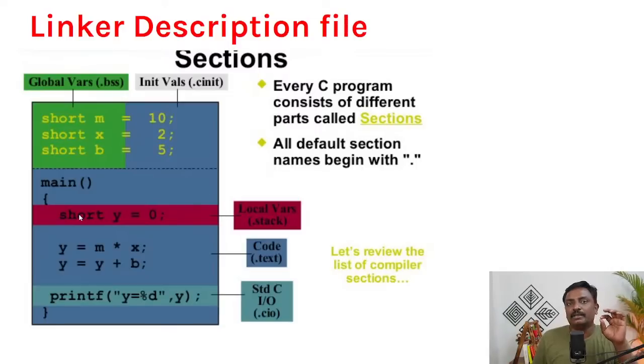Whenever you go for a microcontroller, there are two types of memory available. One is the flash memory, which is non-volatile. The other is the volatile memory, which is the RAM. When you do arithmetic operations, the variable value will be changed, so you cannot store it in the flash memory, because the way you read and write the flash memory is quite different. Flash memory is non-volatile, which means whenever you power off the microcontroller and power it back on again, the program code will still be there.